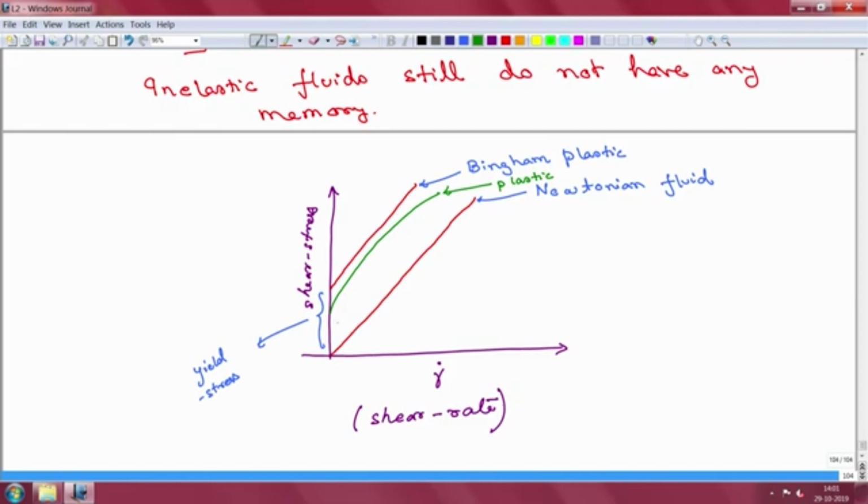So, the material starts to flow after a certain critical stress has been exceeded, but then the shear stress does not behave linearly with shear rate. In fact, the shear stress decreases as the shear rate increases, or in a sense effectively the viscosity of this material decreases as the shear rate is being increased. So, this is an example of what we also often call the shear thinning phenomena, where the effective viscosity decreases as you increase the shear rate.